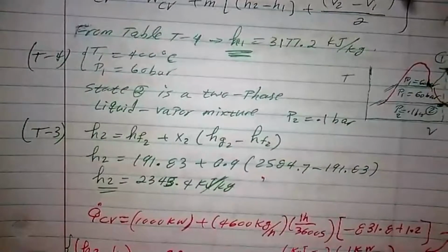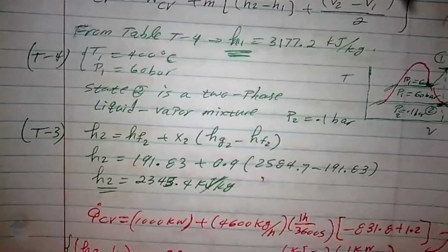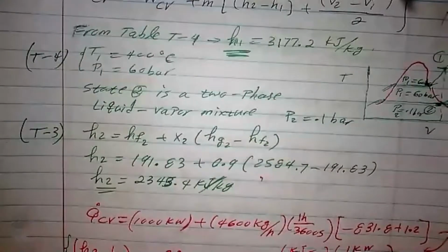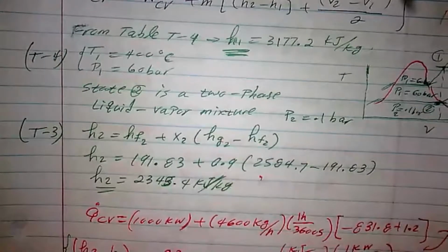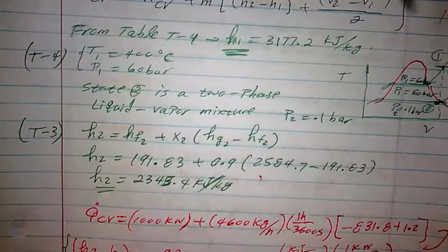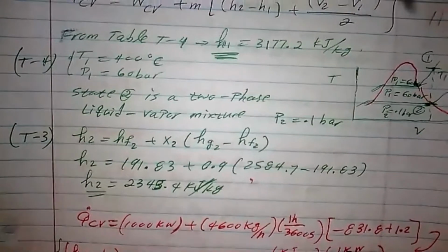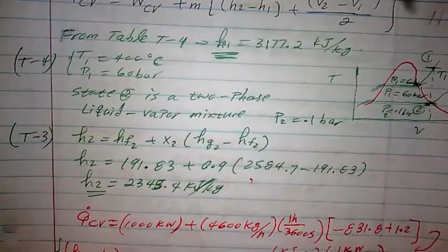find the change in enthalpy, not internal energy, okay? Because it's an open system, okay? We're not going to use CV, okay? And here we don't need to use CV, CP because we're dealing with steam, okay, with water. So it gives you error if you do that. So we need to use the information from the table.